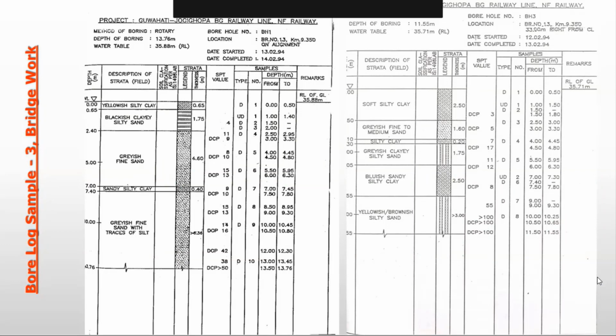So for any location, you take a 300 mm slice and the number of blows is converted into the SPT value. So here at depth 3 they have chosen. So they are taking 3, but it will represent a value from 3 to 3.6.